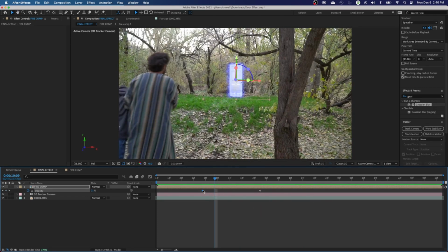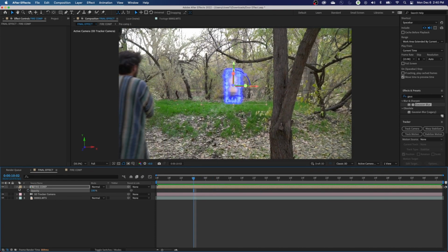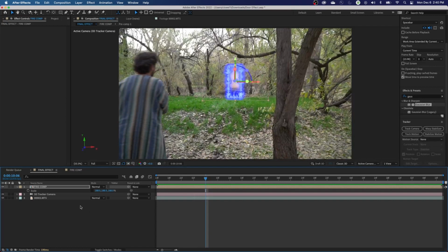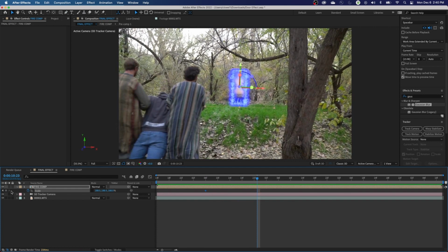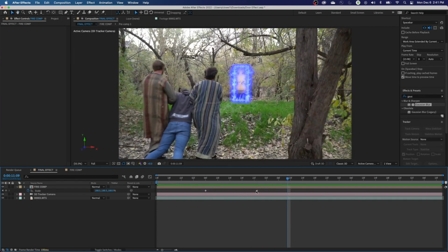If we want something that looks a little bit more like a portal opening up, let's do a scale change here. So I'm going to hit S for scale. We're going to unlock the scale here, and we're going to animate this. Let's have it happen right about here. We're going to turn on a keyframe for scale, and then an ending frame right here, add a new keyframe for right there. Jump over to the previous keyframe, and let's make this go flat like that. So we'll just put that on 0. There we go. And something like that.